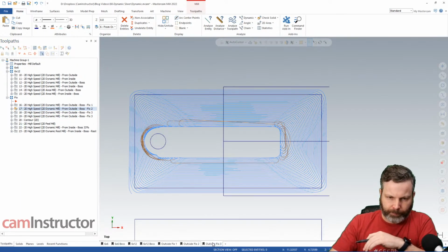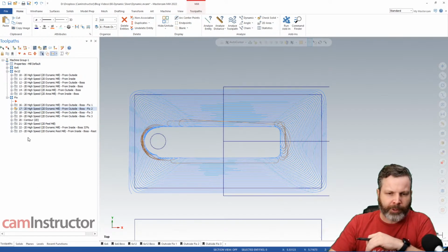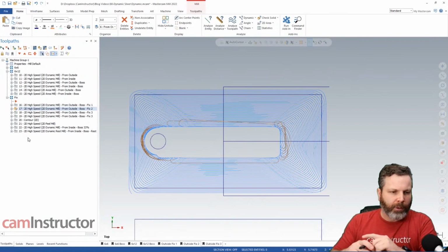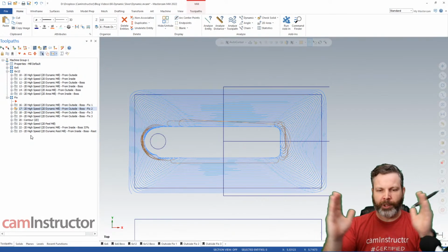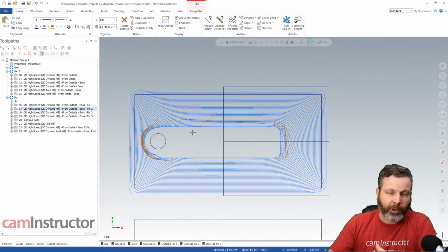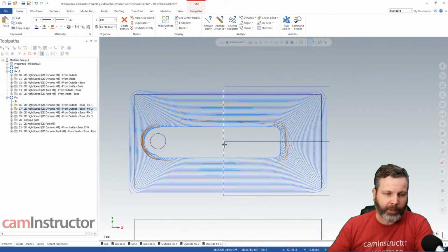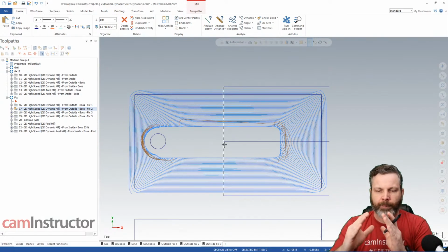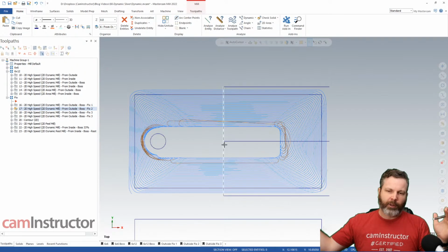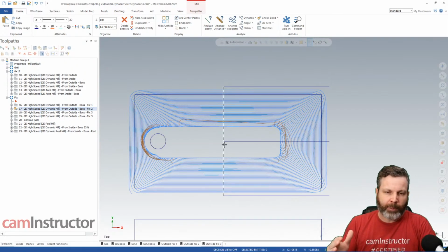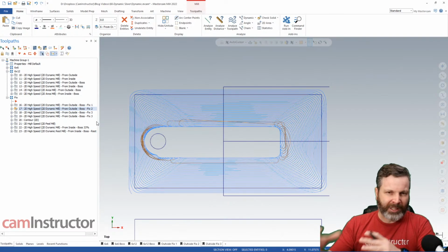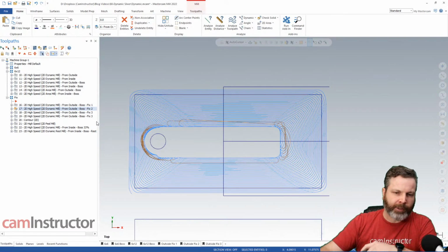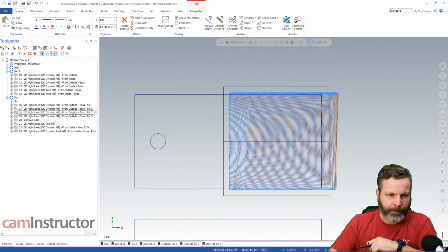Other options, let me go for maybe the most obvious one, but before we get into more of these, another way you can look at fixing this toolpath is you just need to eliminate the disproportion between the width and the height. If you can get that squished down to being more of a square-ish shape, the closer you get to square, the less sliver there'll be here, and the less you need to worry about it altogether. So you don't need an exactly square part, but if your part is 20 inches long by 2 inches tall, if you can squish that 20 inches down somehow to maybe 6 inches long by 2, that will probably machine just fine. So we just need to look at different ways we can squish off that excess that's out of proportion in this toolpath.